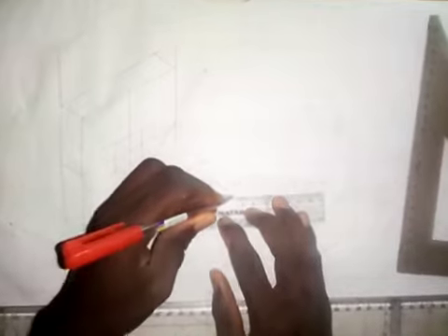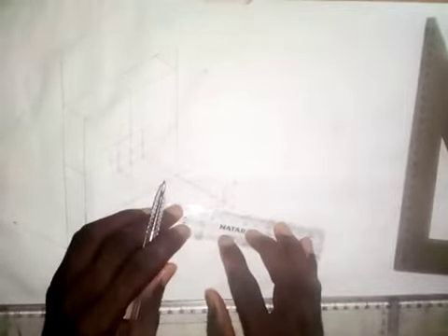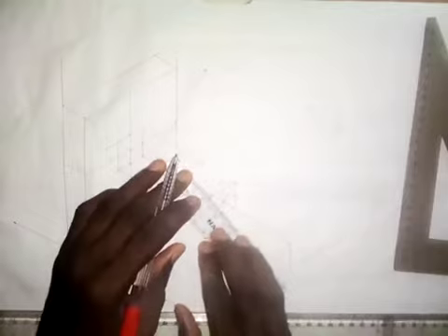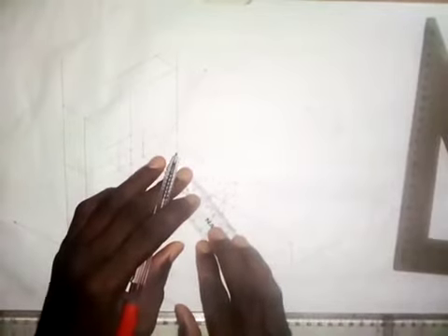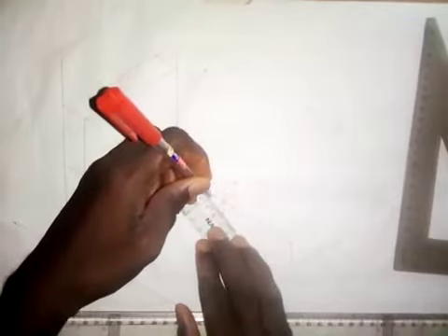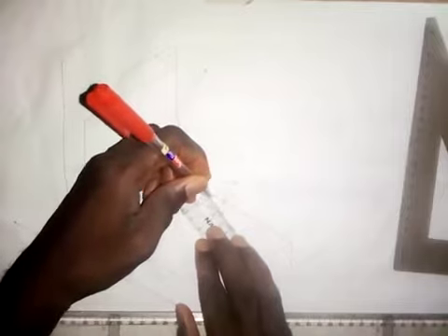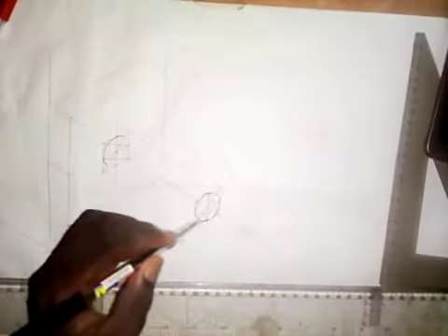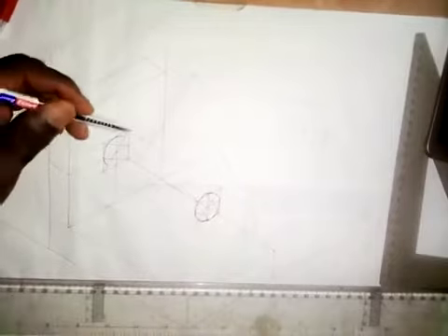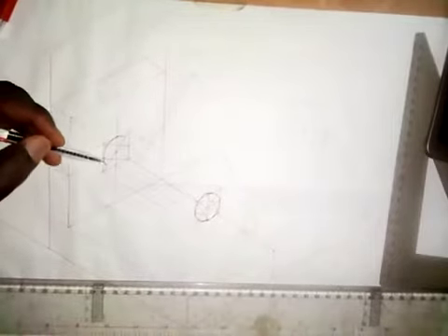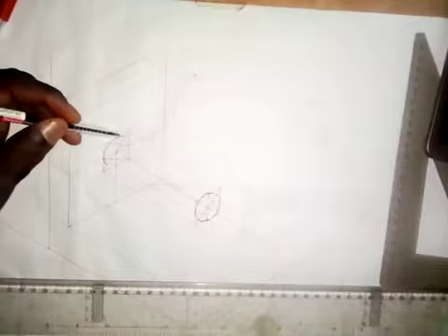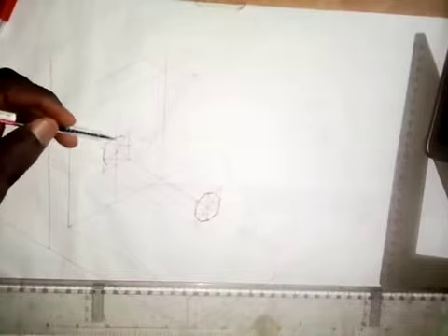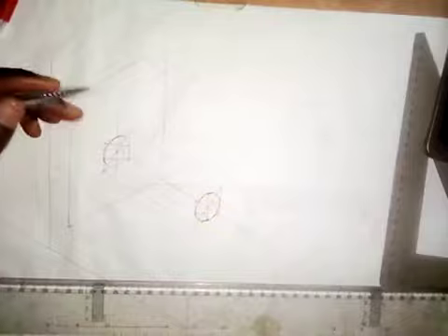So I believe that you know how to draw an isometric circle, because that is what I want to do here. I'm going to draw the isometric circle, then I will show you how we can form the cylindrical part. All right, I've drawn the isometric circle as you see here, and here we are not to draw the whole of the circle, so you only need to produce a little part of that. I think this half, yeah, just produce half of it. Then we are going to form the cylindrical part like this.